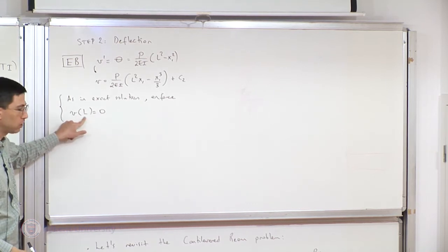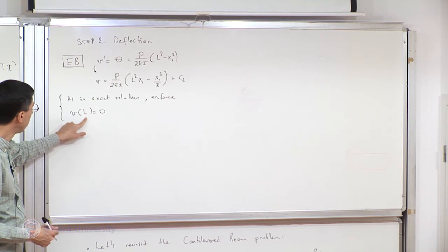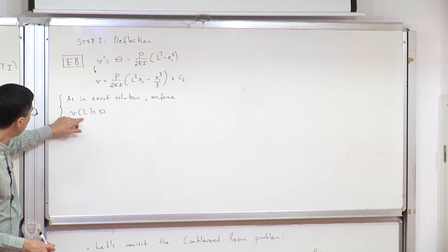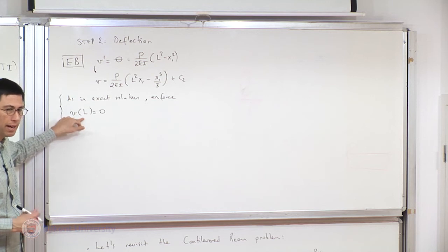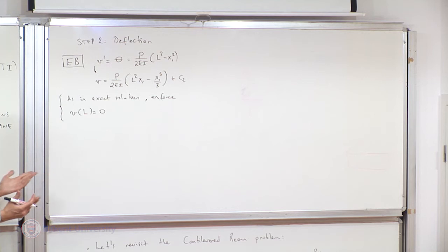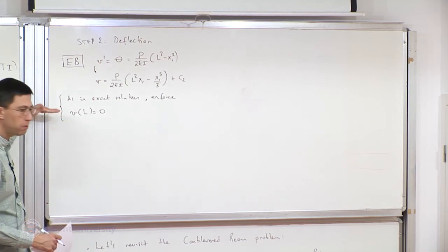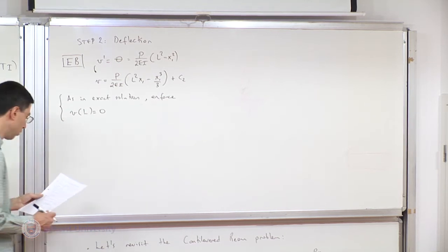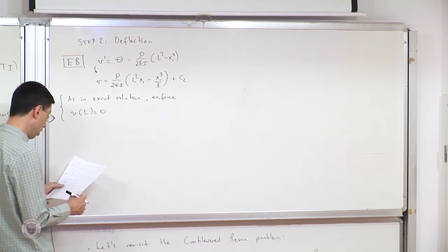The vertical displacement was enforced to be 0 in the analytical solution, I should say, not the exact, but anyway. But at any other point other than x2 equals 0, in other words, along the neutral axis, it was not necessarily 0, because we had to somehow relax our constraints. Only along the center line, along the neutral axis, we enforce it to be 0. So with beam theory, that correlates very well because we're only looking at the neutral axis deformation in this case.